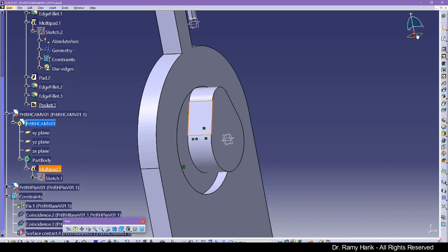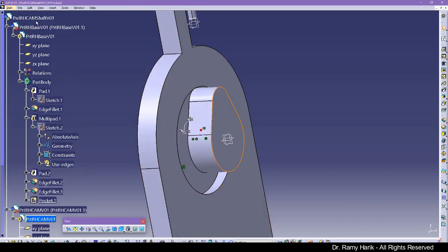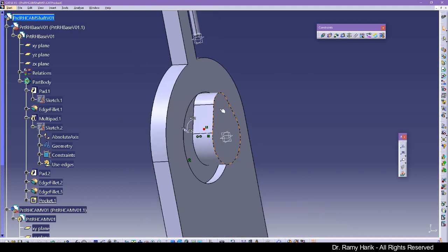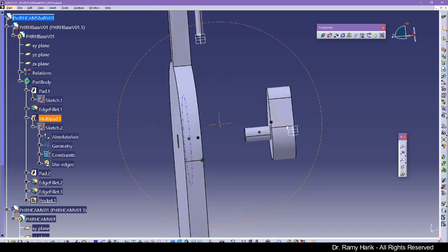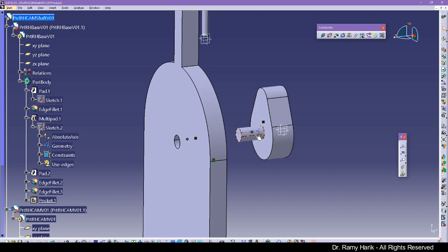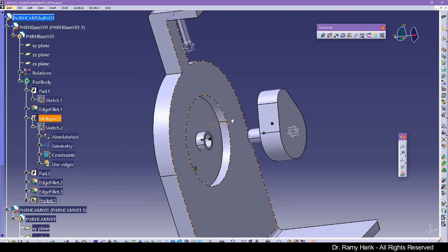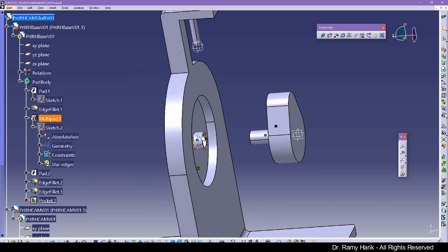So let's go ahead and see what we're talking about in here. If I bring this here and I move this, you should never do this when you're in a part. You should go back to the assembly and do this here in the assembly, because in the part you would change the part reference. So what we can do is, if we wanted the part in here to mount on this one and not to have this collision in here, create this 20 millimeters hollow area.